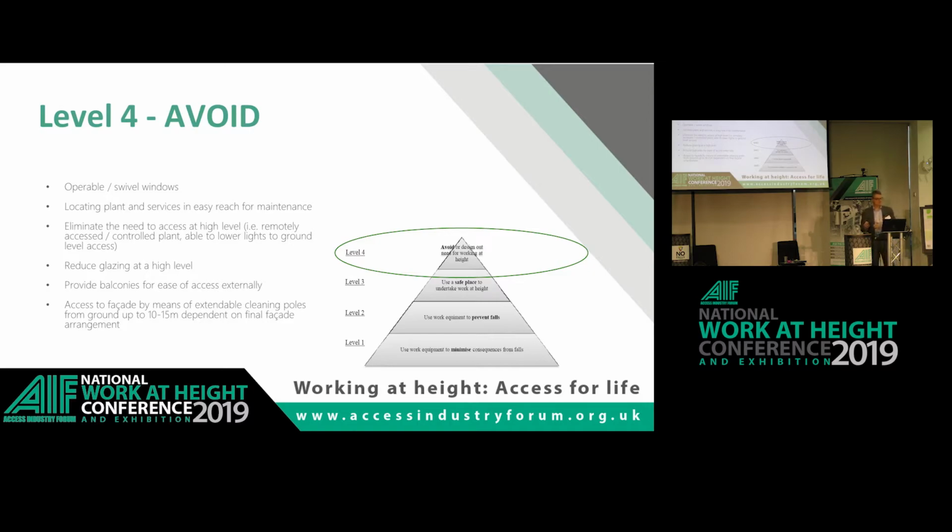That's not always possible, but in some instances, such as residential blocks with small windows, it is possible to minimize the amount of external access by making sure you've got openable windows. Brilliant. We've avoided access at height. We now don't need to deploy someone off the side of this building to clean the window outside. We've avoided it altogether. Now, that sounds really simple, and we should basically make all windows open inside.